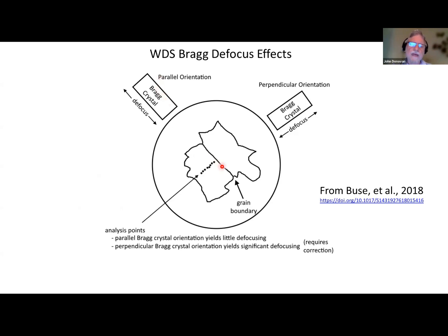Depending on the orientation of your boundary to your WDS spectrometers, you can get a defocus effect or not. If the boundary is parallel to your Bragg crystal, then you do get WDS defocusing.